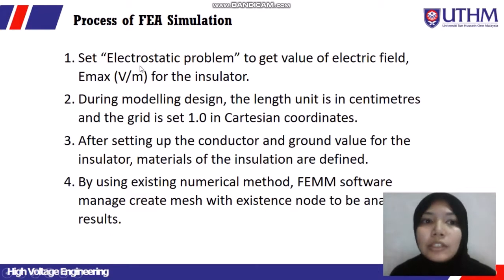Like I said before, we need to set the electrostatic problem. Why? We use this because we need to get the electric field Emax in V/m for the insulator. During modeling design, the length unit is in centimeters and the grid is set to 1.0 in Cartesian coordinates. After setting up the conductor and ground value for the insulator, the materials of the insulator are defined. By using the existing numerical method, FEMM software managed to create a mesh with nodes to be analyzed for the results.